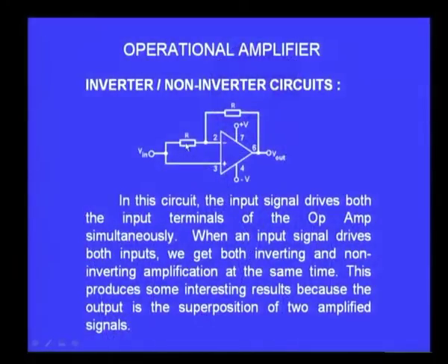It is inverting whatever is the amplitude at the input correspondingly at the output. It just provides 180-degree phase shift between the input and output. So, when I ground the non-inverting input, the amplifier becomes a very simple inverting amplifier.